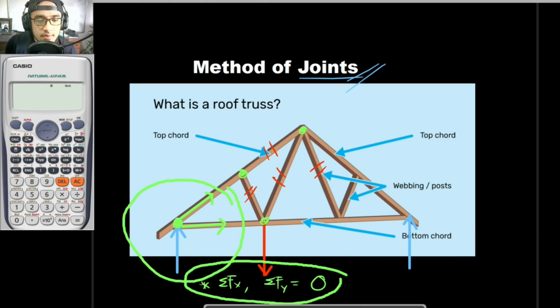By tension, so for example that we would be analyzing this joint right here. Once again, your tension is to be in a pulling action, in a pulling manner. So meaning our force would be away from the joint since it would be pulling. So this would be tension, this would be tension, and this would be tension. If once again you would be considering this joint right here, it is better for us to consider this in tension, this one in tension, and this also in tension. So once again, you would be assuming that your bars would be pulling your joints, so tension.